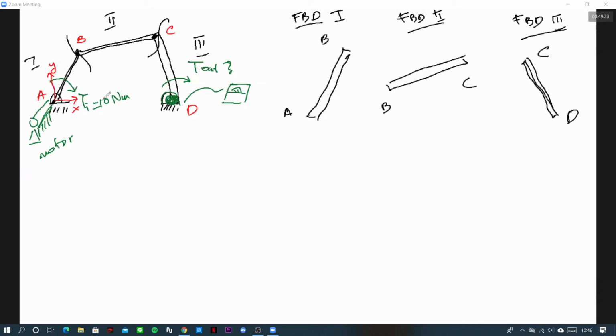If you take a look at the left picture, we have a 4-bar linkage. So each point has a joint. So it means each point has a reaction force. Here we have a reaction force in the x direction, RAX, and then RAY. Then here at point B, because this is also attached to a joint, we can write it like this, RBX and RBY.